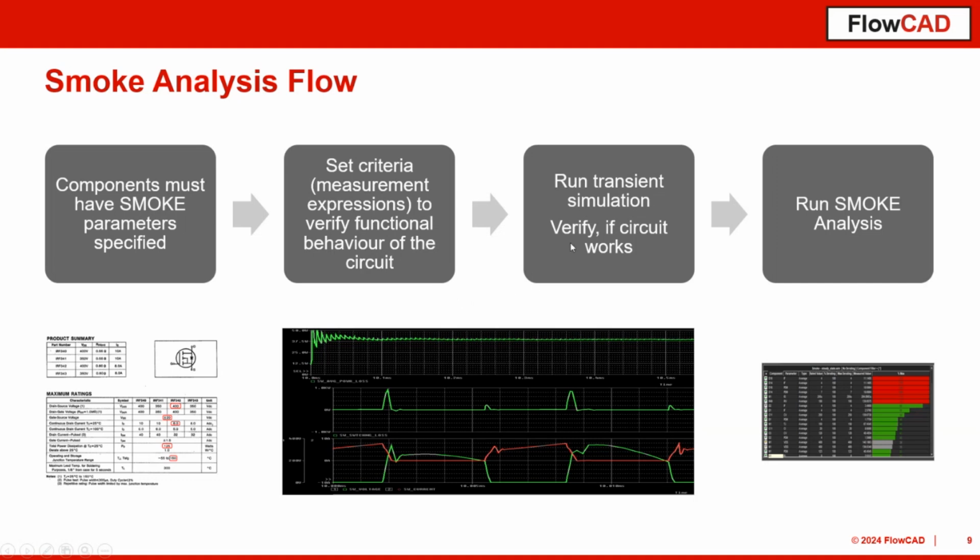So that is your normal implementation and design work when you create a circuit. You just check if the circuit is doing what it should do. And you're running your simulations like transient simulations, frequency-based simulations, and so on. And you verify, yes, my circuit is doing exactly what I want it to do. Normal process. The one additional step you have to do is just clicking one more button, and that button is run the smoke analysis. That's all. There's no additional work to be done here. Just click this smoke analysis button.